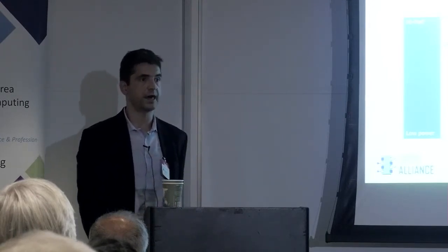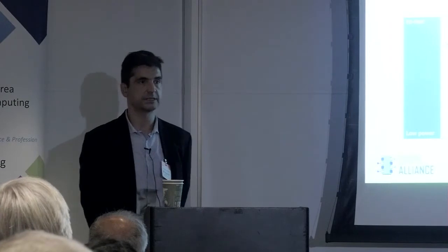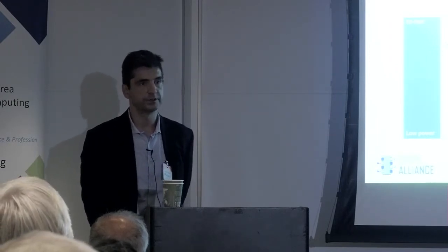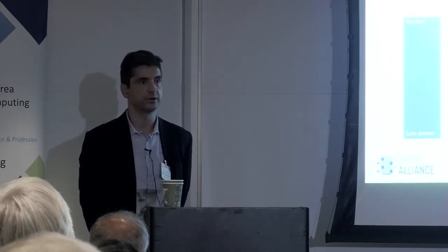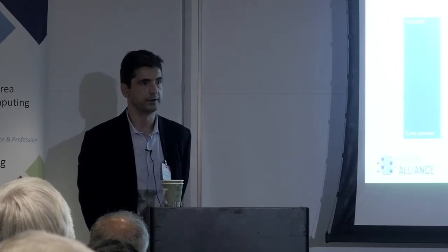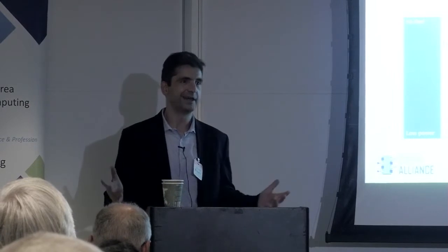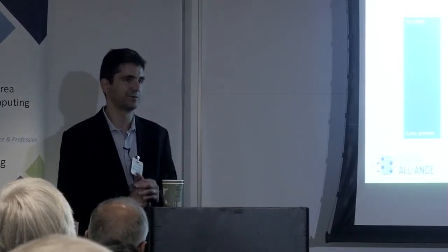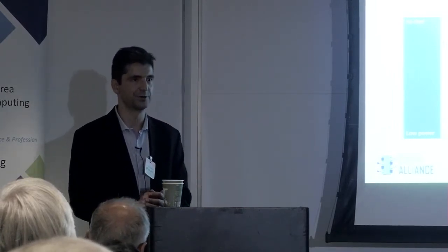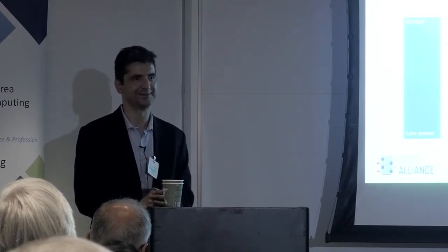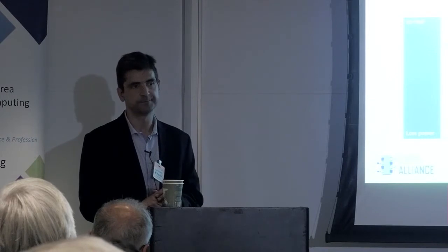The flow that we have is we mostly design our IP in Verilog. For the design verification, we use SystemVerilog. And then we use commercial tools, except for Verilator, everything else are commercial tools because we have a product to build. So we can't really play yet with open source flow. But in CHIPS Alliance, we want to tackle that.